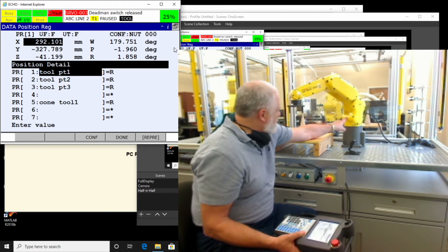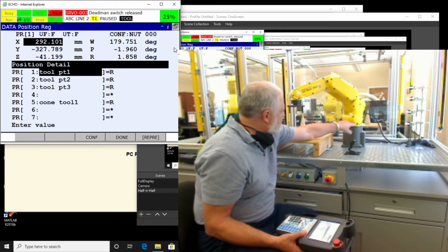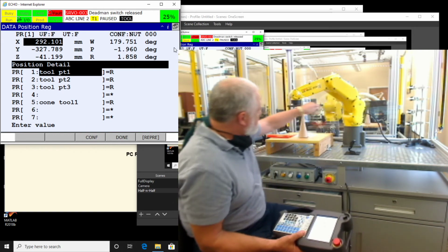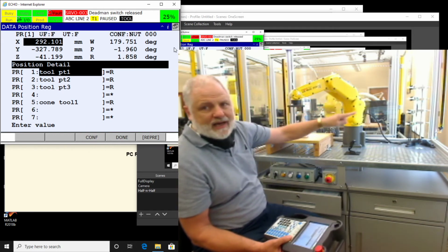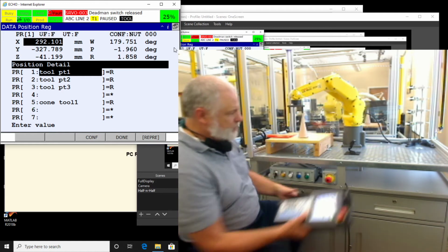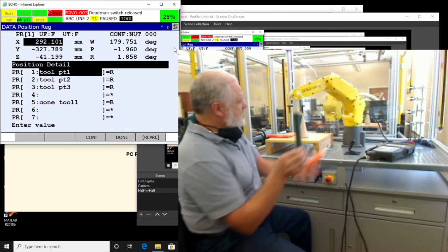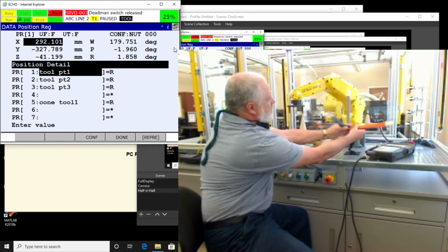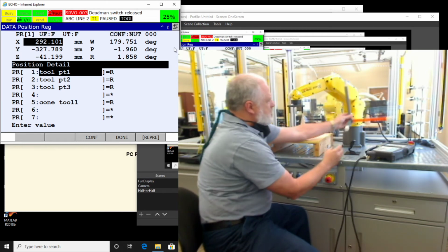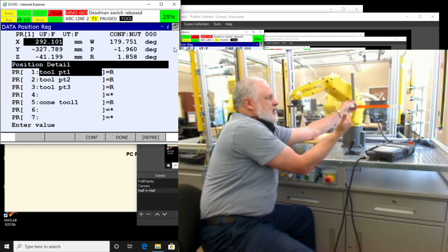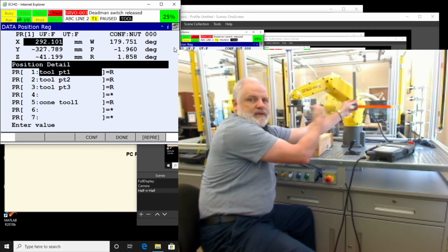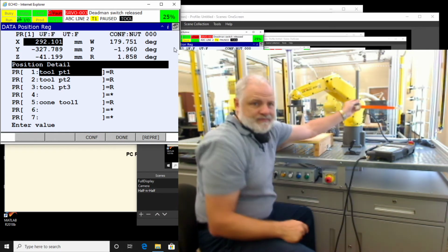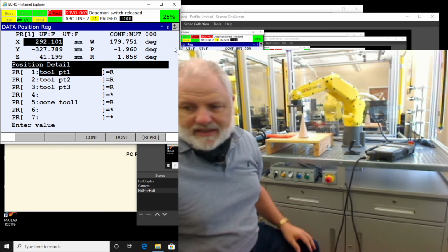So that origin, actually it wasn't right here. Sorry, this is the joint. It's the second one. So it's coming out straight out from the robot. Where's my Cartesian axis here? So it's coming straight out from the robot in the X direction, and then minus Y, so it's going in the minus Y direction, and then it's going in the minus Z. Okay. And that's why we see those numbers there.